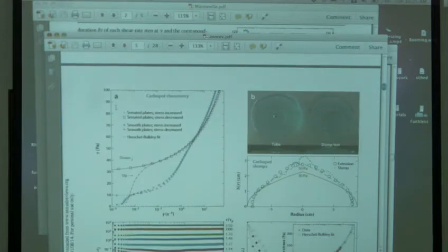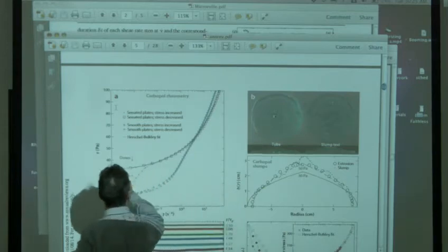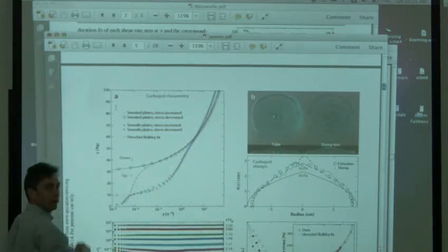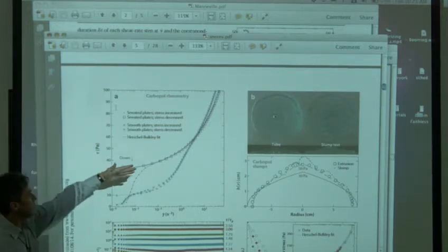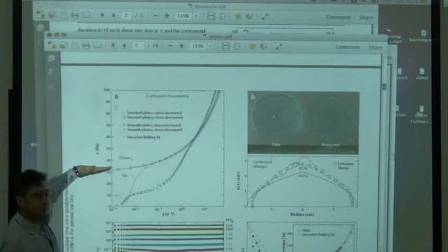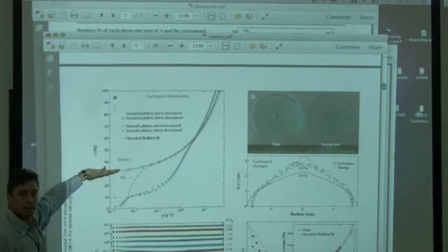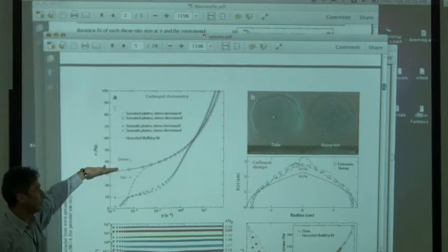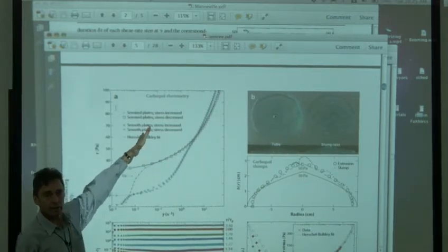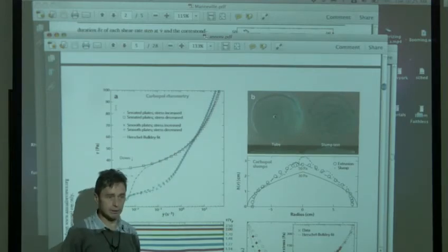Okay, so here's some actual experimental data for this stuff, which is hair gel. So you've got a flow curve that does something like that, right? So the Newtonian behavior is a straight line through the origin. This is a semi-log plot, okay? But what hair gel does, for example, is it has an intercept and then it has a nonlinear curve here. So the intercept corresponds to the fact that it's got a yield stress. You have to push it hard enough to get it to move. And once it's flowing, the viscosity varies with the rate of deformation, the shear rate. So that's characteristic of these kinds of materials.